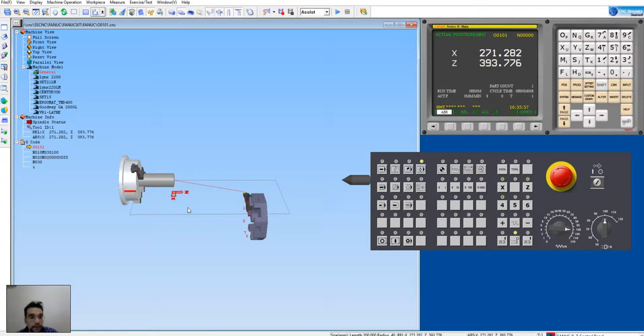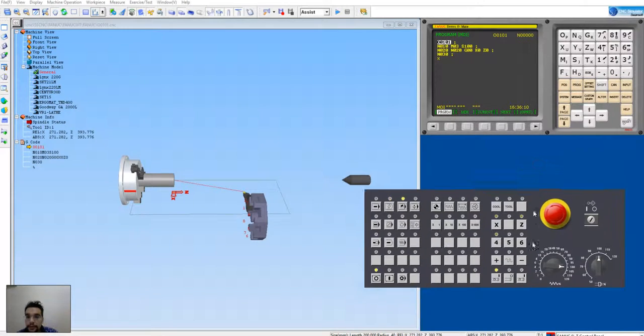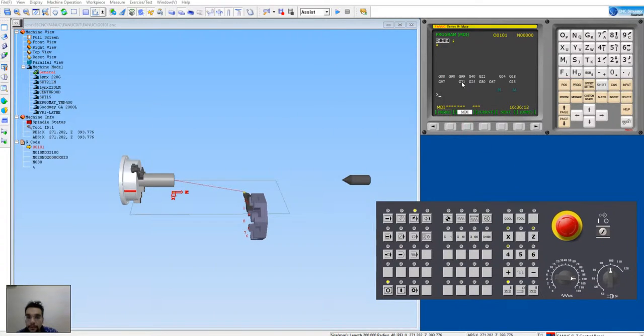It's okay, I don't have any problem with it, and we okay it, and everything's cool. Let's start it. For starting this, we need to go to MDI mode, because this just doesn't work. You can't just work with this. We go to program and the MDI part. Let's say M03 S100. This is okay. We can run it with this one. Sound okay, it's running fine.